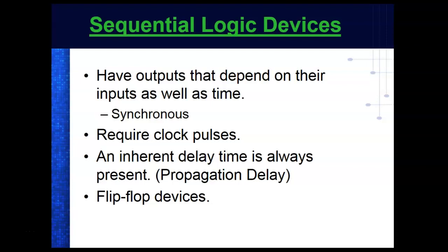So these timers we're going to be dealing with are going to be software timers. But if I wanted to keep up with like an incremental encoder running a motor, there ain't no way in the world that a software timer is going to keep up with that thing. So what they've done now is they've added what they call high speed counters inside the PLC, which is hardware. So they've actually gone back to hardware timers, and I think this guy right here's got 3 in there. They didn't understand that until these motors and stuff would run away with it.